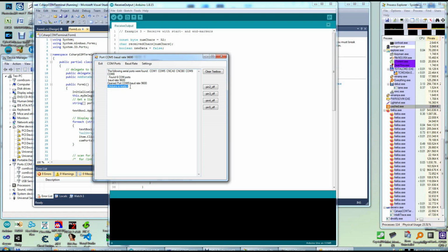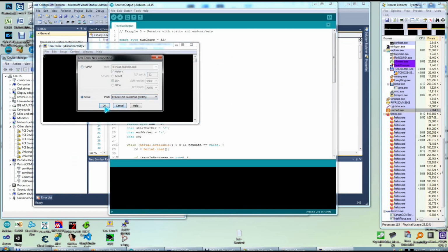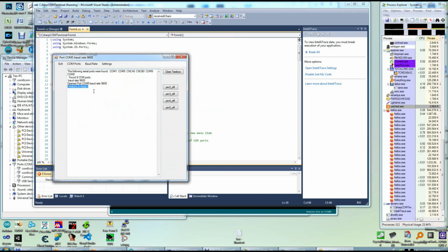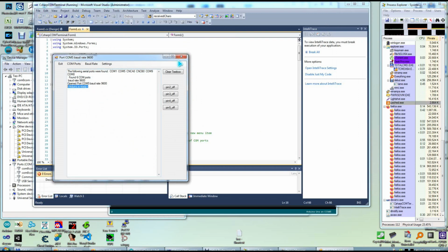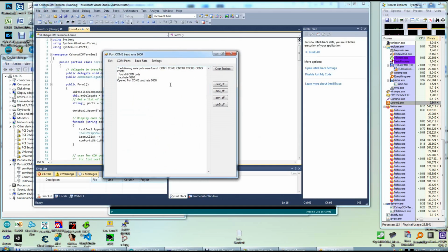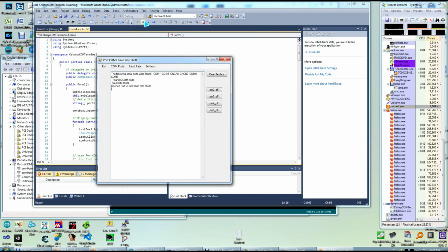This little acknowledgment appears only if I open Tera Term first. I change to COM5, press OK, and receive it here, and now I'm closing it. Now I'm opening here, and Arduino is ready, and I receive it. Until here, it worked by the book, perfectly. Now I'm closing it, and when I open it again on the same COM port 5 and the same baud rate, so exactly the same address as before, I am not receiving it. Every time I close and open this program again from C#, I don't get that Arduino is ready acknowledge string. I don't know exactly the cause, but it works when I open Tera Term on COM5, close it, and then the first time I open this, it will work correctly. But after I close it and open it again from there, it will not work.